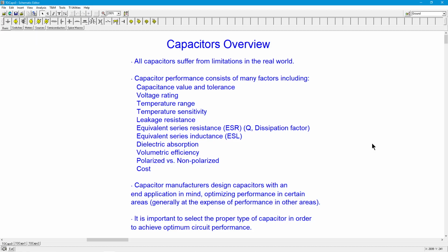Okay? High volumetric efficiency means for a certain amount of capacitance, for 1 microfarad, high volumetric efficiency means the case itself, the capacitor, the thing you're going to solder into a board, is physically smaller. So generally speaking, we would like high volumetric efficiency. But as you can guess, you're not going to get that for free, right? That depends on the dielectric that you're using.